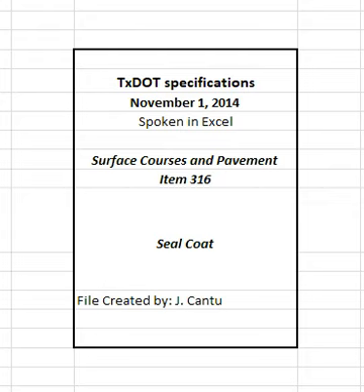4.10 Rolling. Start rolling operation on each shot as soon as aggregate is applied. Use sufficient rollers to cover the entire mat width in one pass, i.e., one direction. Roll in a staggered pattern. Unless otherwise shown on the plans, make a minimum of 5 passes, or 3 passes when the asphalt material is an emulsion. If rollers are unable to keep up with the spreader box, stop application until rollers have caught up, or furnish additional rollers. Keep roller tires asphalt free.